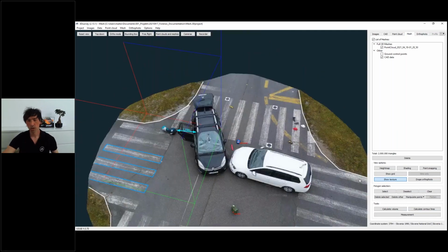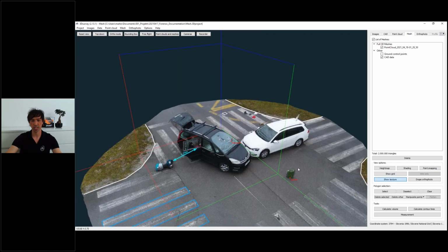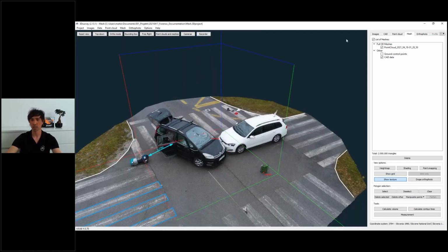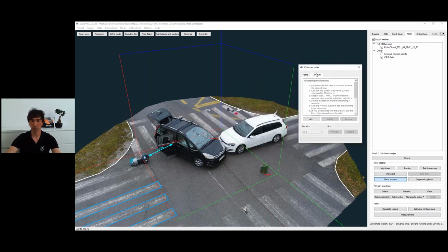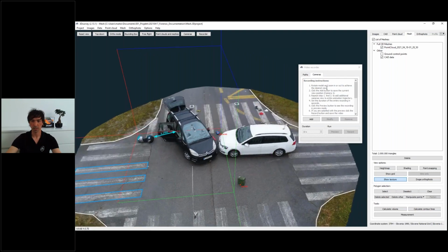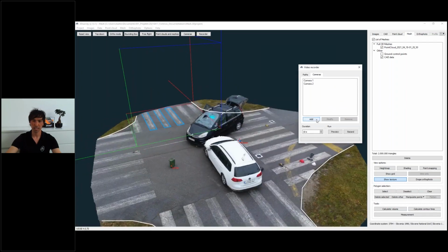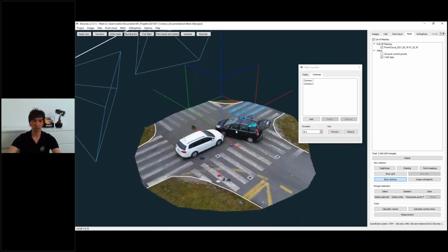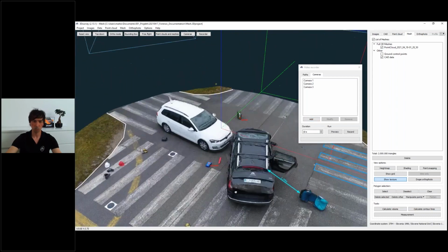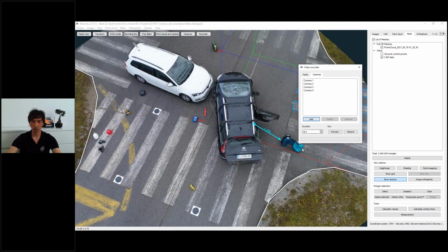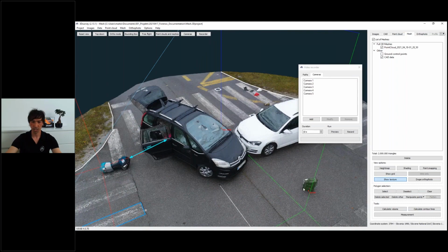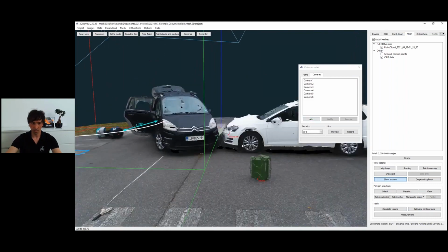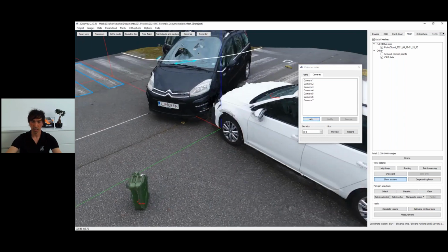with which you can do fully realistic fly-throughs based on your 3D models, and it is super easy to use. Just click on recording, and then the video recorder pops up. It asks you to set the first camera position and click on add. Move the model a bit, add another camera. Let's go a bit further, add. Now we would like to go a bit closer, and now I'm actually adding camera positions to generate a video presentation. So move it like here, add another one,